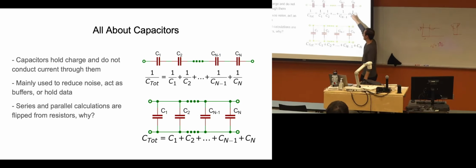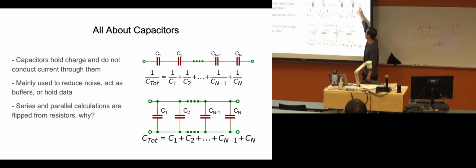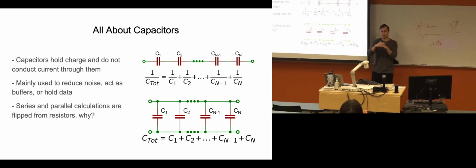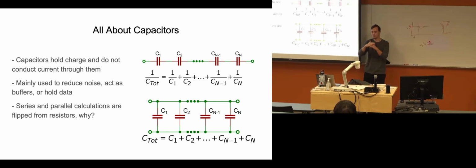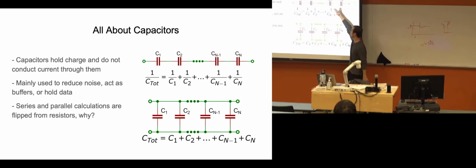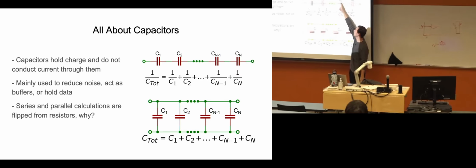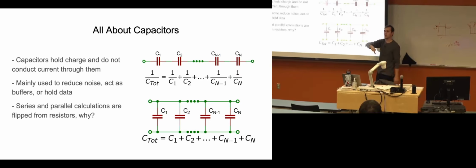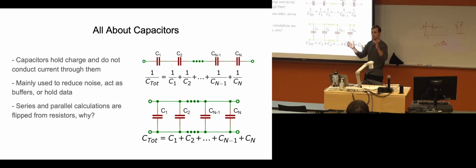If you have 2 in series, you have a voltage here, and then you have some intermediary voltage, and then less voltage. The capacitance on a capacitor is actually determined on how far apart the plates are from each other, right? The closer, the more coupled they are. By physically putting 2 in series, you're essentially making it so this plate is coupled with this plate. So the total capacitance will go down because they're further from each other, right?